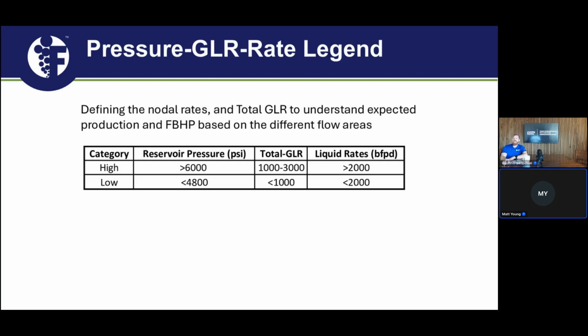One of the big key takeaways we found came down to two things. One, of course, picking our correct flow path. And secondary to that, when do we convert? We found that total GLR, TGLR, and for anybody unfamiliar, GLR is gas to liquid ratio, as your total GLR increased, the time between conversion extended as well, and you were able to flow at much greater rates in a much larger flow area.